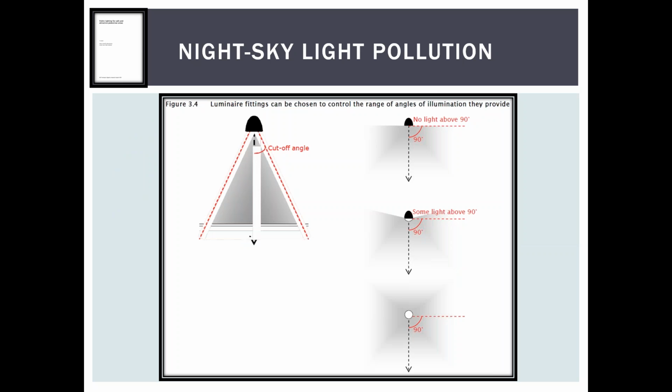This is a diagram from a study done by the New Zealand Transport Agency. The potential for pedestrian lighting design to produce spill light should be assessed both within the lit area and more broadly outside the subject area. Physical measures and careful consideration in the design of a pedestrian lighting scheme can restrict glare and spill light. For example, luminaires should be positioned and aimed to minimize bright light shining straight into a person's field of view. Luminaire mounting heights need to be carefully considered for all likely users of a lit space.